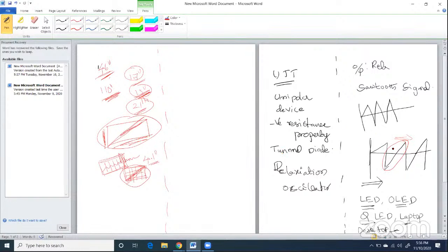This diagonal length is nothing but the sawtooth sweeping length. This is nothing but the diagonal length of any screen. So in order to display the picture, waveform or video on screens of LED, laptop or desktop, or if you want to display the waveform on CRO screens, this is the signal used for the sweeping purpose.